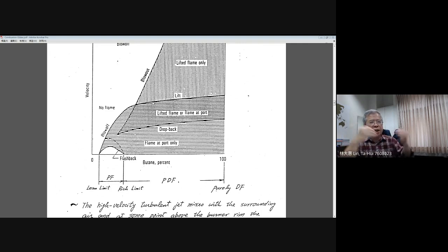Between these, you can find the stabilization limits have a connection together. You can figure out here the blowout region is connected continuously to the line of the lift-off. There are connections, and the blowout line just has an attach point with the line for the drawback. They cannot go through the premixed flame region. But this part we call belonging to the partial diffusion flame.